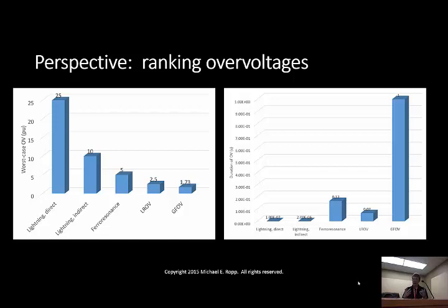That situation was bad enough that it caused huge problems in the plant. The mitigation in that case, by the way, was just pop both breakers. Don't just trip the high side one by itself. But you can see that ferroresonance, under the wrong circumstances, can be a very scary situation. It's kind of hard to know when it's going to be a problem. So there are lots of papers written on this, and we can get into that later, but that's not really the subject we want to talk about today.